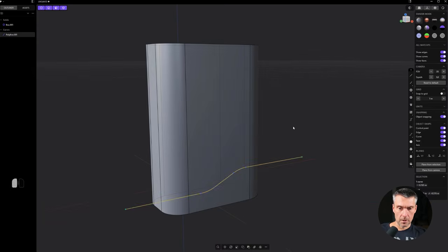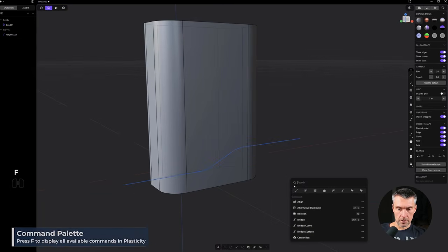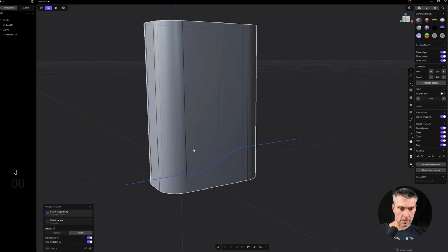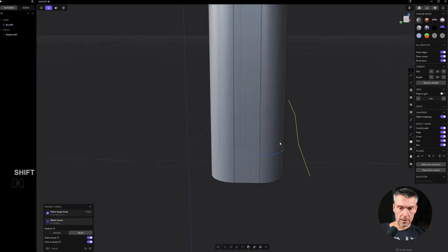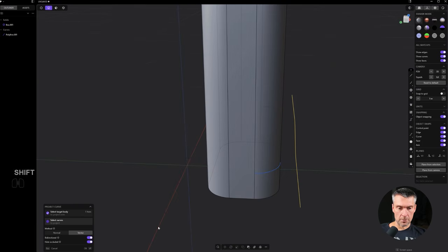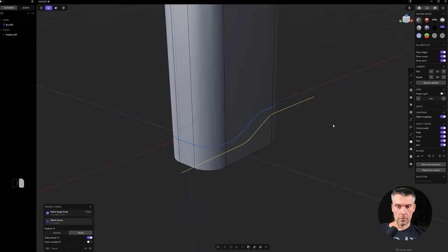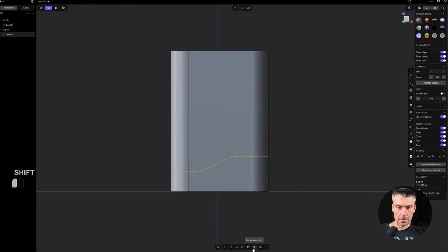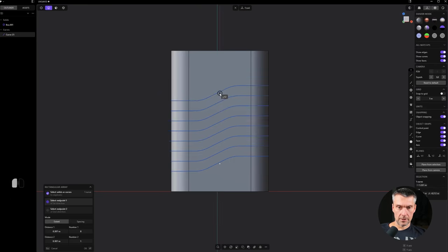So watch. I'm going to deselect this, right? I'm going to go here, and we're going to go to project, okay? So project and click that. We're going to click the body, and then we're going to click the curve. Now, we only have half of the projection, but if you uncheck this here, hide occluded elements, it's going to project and conform to the surface all around, right? So now you can nuke this one, grab this curve, and now you can array this up like this, okay?